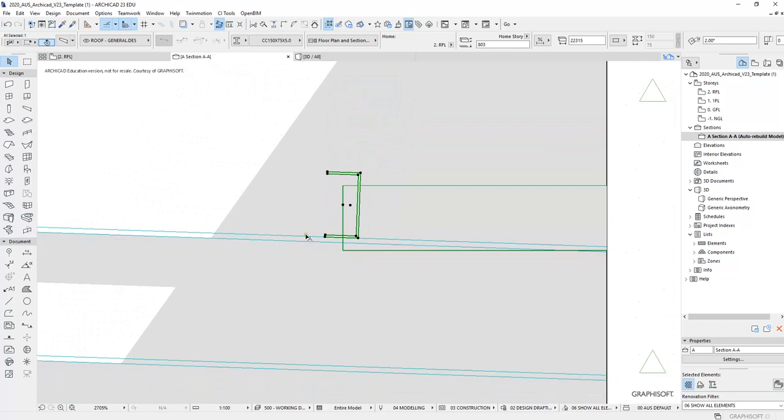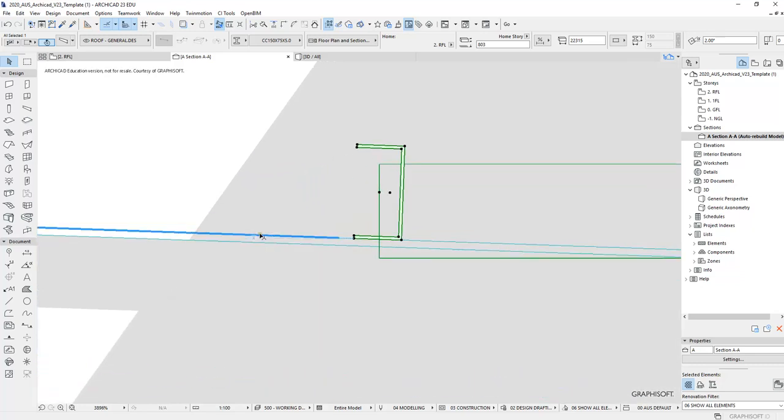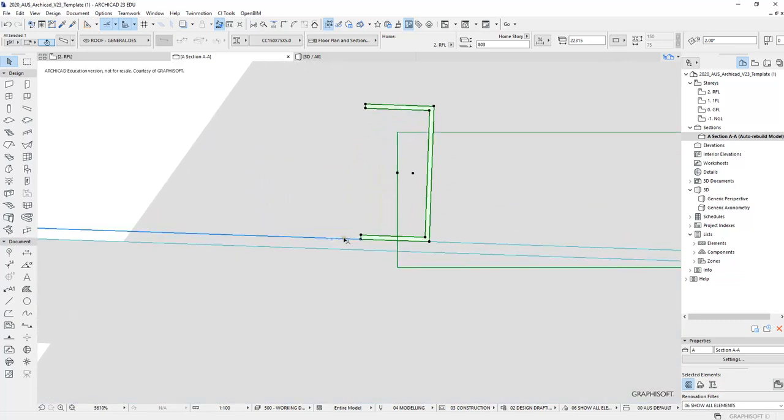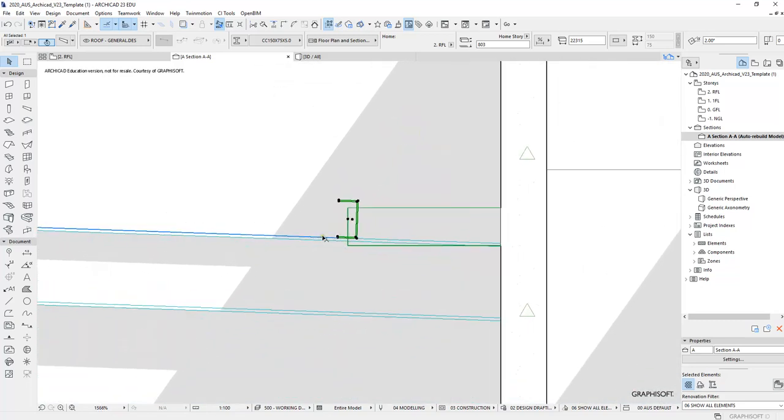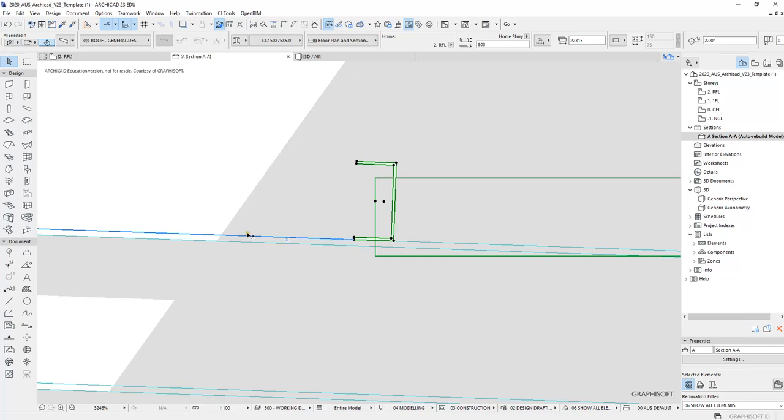So what you can do here is this. So I'm going to place my cursor along this universal beam because I know this is 2-degree pitch. And then after that, I'm just going to hit Q. So Q is the quick way to call out that little blue circle that always shows up every 5 seconds where your cursor is. So Q is doing the same thing as well. So once I hit Q, you will see this blue line.